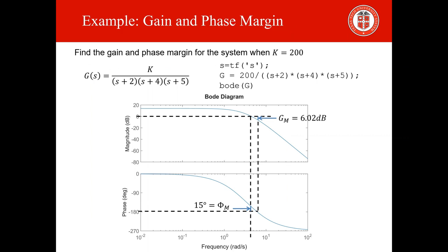So you have this transfer function, G of s. Remember, this is where G of s is appearing here. And then we have our unity feedback system. Okay, so this is what we're talking about here. This guy, G of s. Right, so this is how we do it in MATLAB. So we plot our transfer function, and we can use this Bode function to get the Bode diagram.